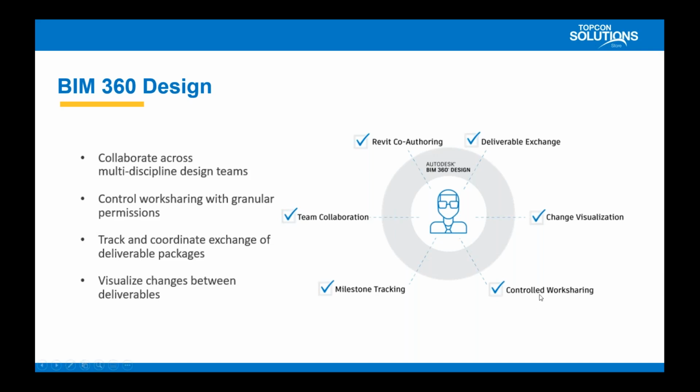Yeah, and to that point, earlier you mentioned pushing field information, install information out to the field as well. So if you're an MEP involved with the design team, you're on a collaborated model, a work shared model, a cloud work shared model, you don't have to change your workflow or create a separate model for the field installers. You might do your details differently for them, but essentially all you're doing is choosing what information you want to send to them, and you can use those publish settings in Revit.